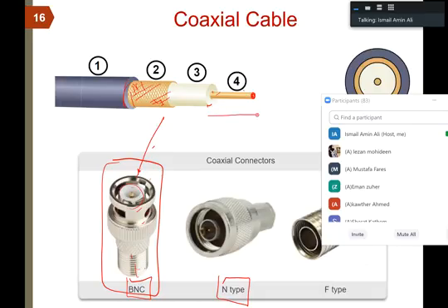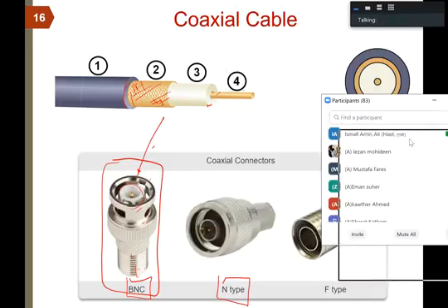This is copper, and it exhibits resistance, of course, and resistance decreases when we increase the cross section. So when you increase the cross section, the resistance decreases. The attenuation is related directly to the resistance. When the resistance is less, the attenuation is less. So, of course, when you have a thicker cable, you have less attenuation because you have less resistance. Okay?